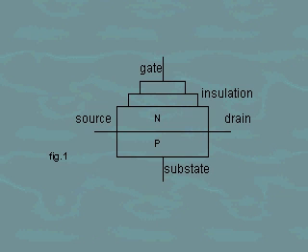Most commonly for a MOSFET, this insulation is achieved by using a thin slice of metal as the gate instead of the usual piece of semiconductor crystal. This slice of metal is oxidized on the side that is placed against the semiconductor channel. Metal oxide is a very poor conductor, so this layer of oxidation effectively insulates the gate. The semiconductor channel is backed by a substrate of the opposite type of semiconductor. That is, if the channel is made up of an N-type semiconductor, a P-type semiconductor is used as the substrate. IGFETs with P-type semiconductors are less common.